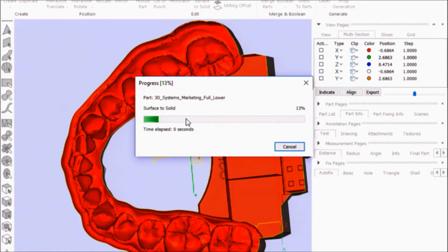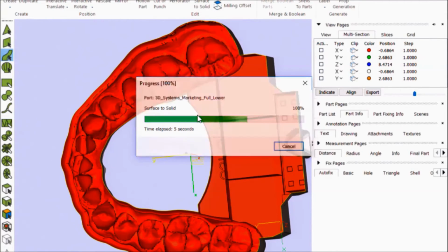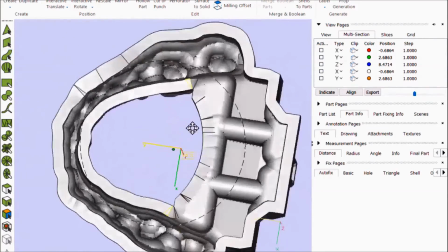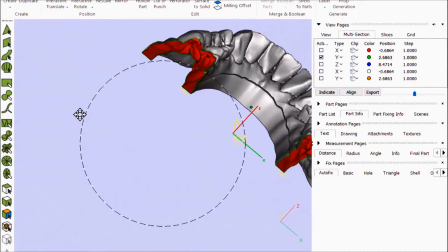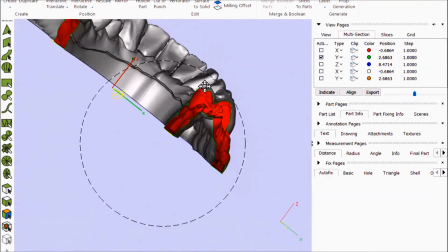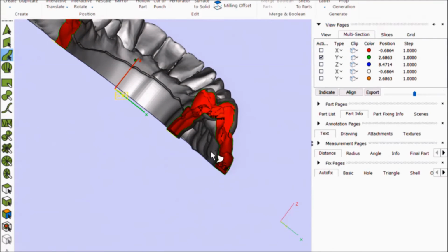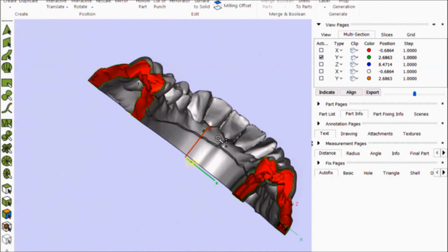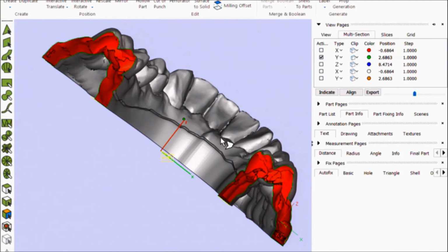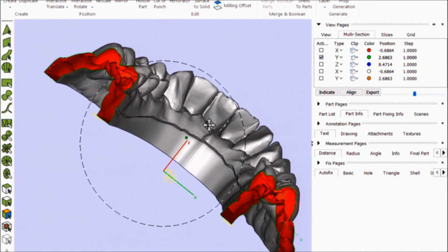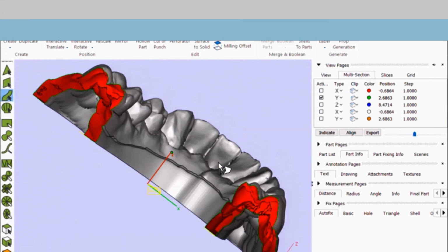So take 30 seconds, but a much cheaper part just by doing that very quickly, ta-da. And now if I take a cross section of it, most of the part, that whole area in there, was just wasted material. I didn't need that. A detail like that could save you a large quantity of money and time and post-processing and all of that just at the design stage.